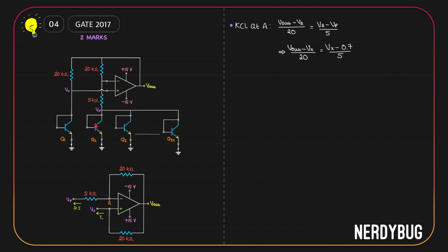So the potential difference between the base and emitter is Vp minus 0, which is Vp. So we can say this is equal to 31I, where I is actually Is e to the power Vp by Vt. Also, this equation can be simplified and written like this. It gives us a relation between Vout and Vx. We get Vout is 5Vx minus 2.8.